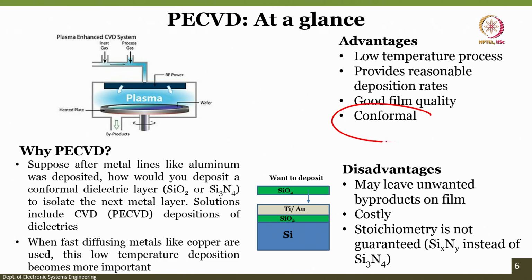Conformity is very important, particularly when we talk about structures which are flexible in nature. The silicon dioxide should be conformal with the structure of the substrate. This we will see particularly when we are talking about implantable devices for brain. So, we will talk about conformity in that particular case.